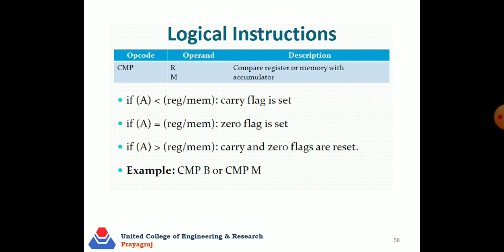So, compare instruction. There is one very important thing, once again: there will be no change in the accumulator or any register. Only the status flags are affected after execution of this instruction, CMP. It is a 1 byte instruction.